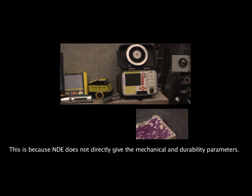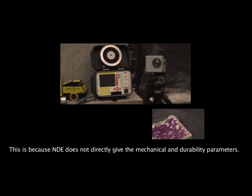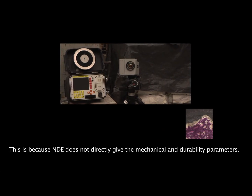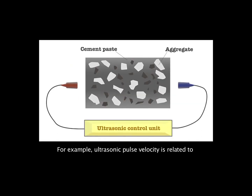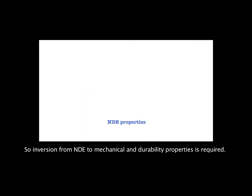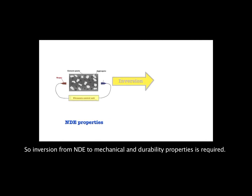This is because NDE does not directly give the mechanical and durability parameters. For example, ultrasonic pulse velocity is related to, but does not directly indicate, compressive strength. So inversion from NDE to mechanical and durability properties is required.